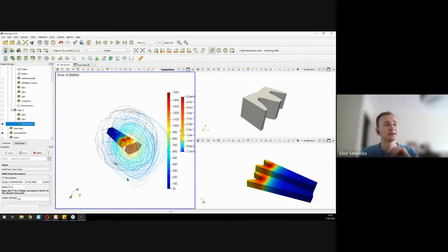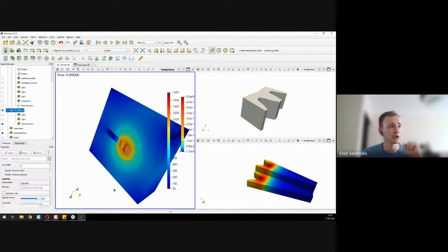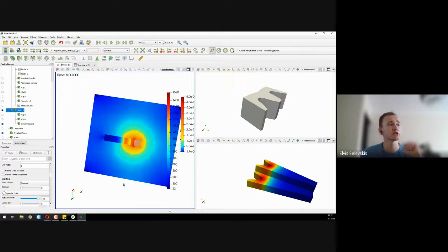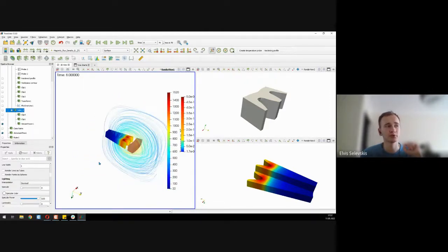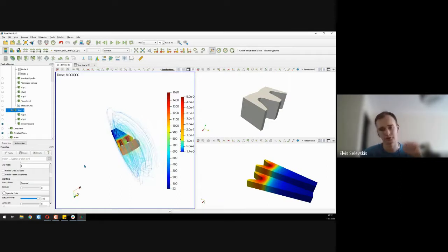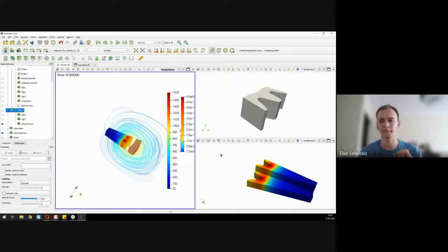Also remember that the limitation here is the actual airbox. So here where we have the airbox, actually the magnetic field lines won't be able to go out of the airbox. So that's also something to keep in mind. Yeah, the next question, I hope I responded to that. If you need me to elaborate more, let me know.